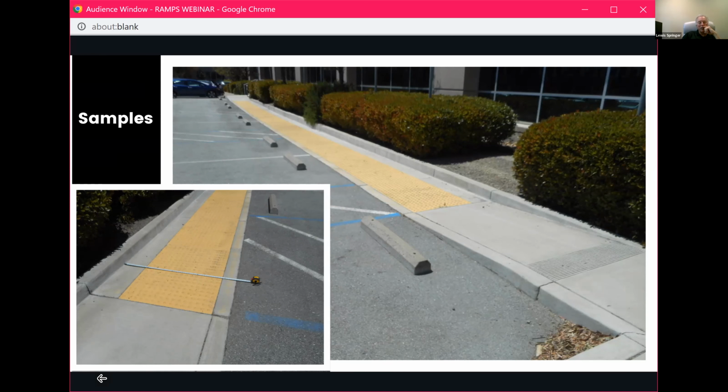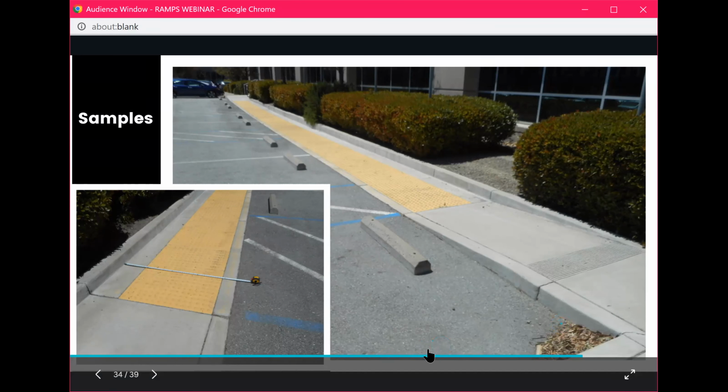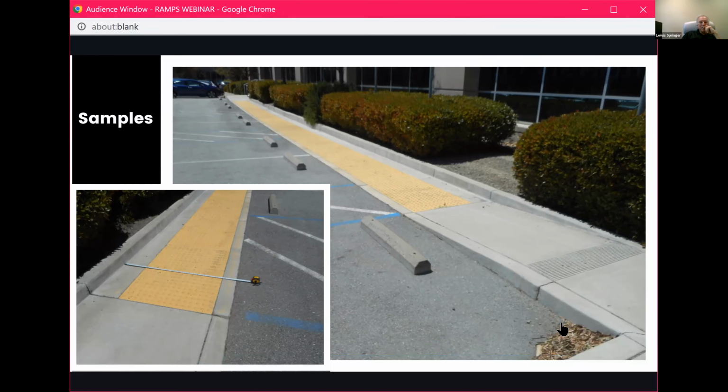If that's a blended transition, yeah, I would sort of. I mean, I think 36 inches of concrete. I think it goes back to the 11B sections where the code talks about you can't reduce a corridor width down to 36 any more than 24 inches in length, rather than maintaining the 44 or the 48. So the question's coming back to that same thing: if your hallway or your corridor or your walkway needs to be 48 at all times, and now we're introducing a hazard because these domes are clearly hazards, then does that 48 need to extend past the domes?